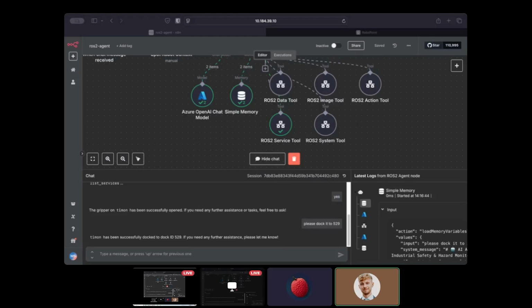And also regarding grasping feedback or force feedback. In the pipeline I just showed, there is no force feedback. But it's a very good input, which should definitely be done in a real production setup. In this case, I just did the grasp, and it's more or less a fire and forget pipeline. But when doing this in real production use cases, it's definitely necessary to use force feedback.